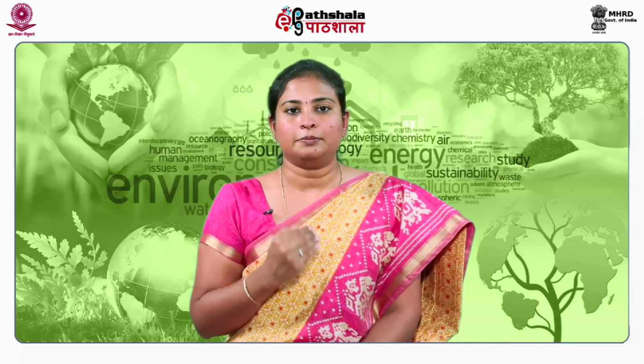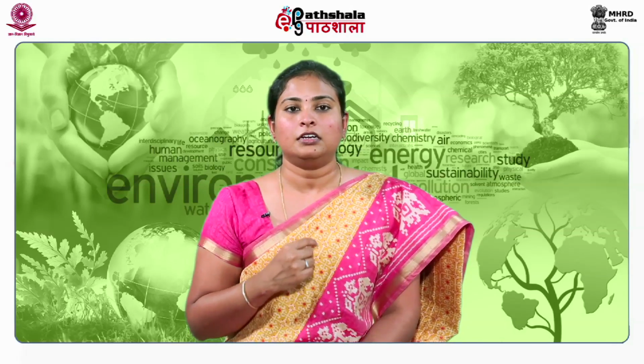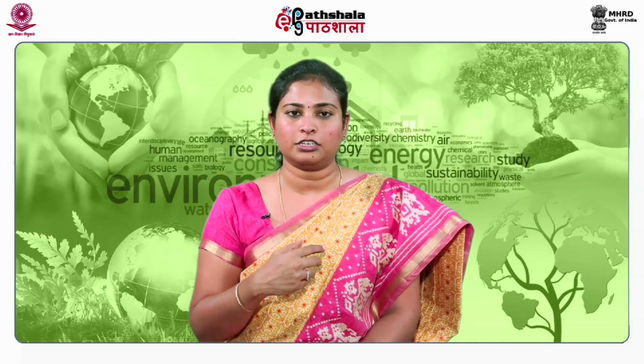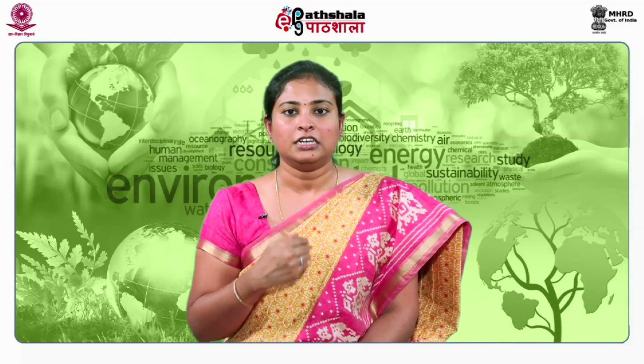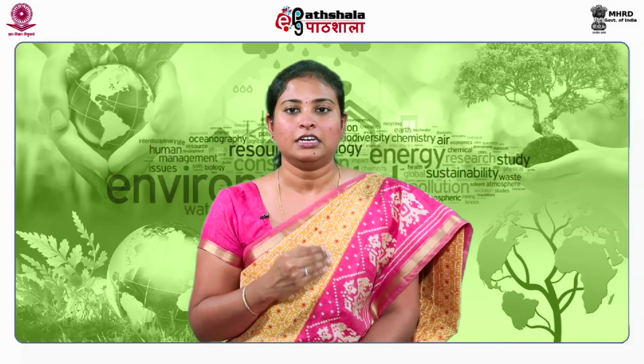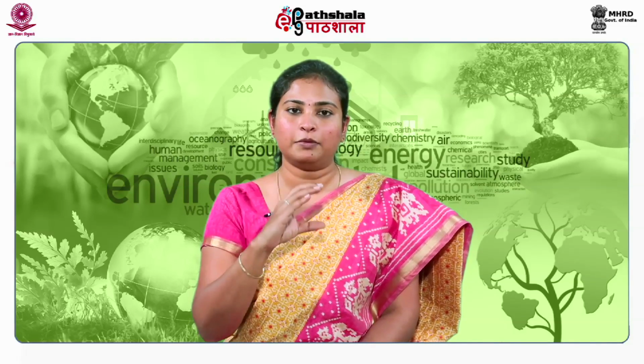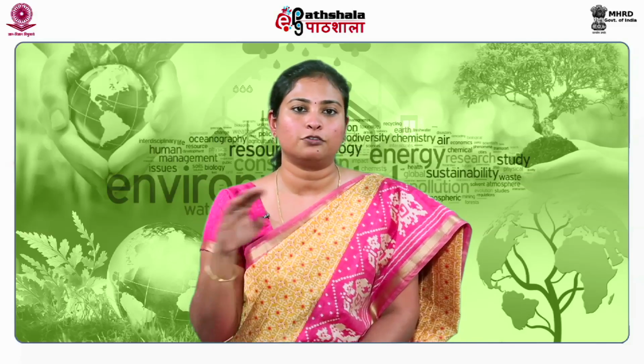Now, the next component is the daily and final cover at the top of the landfill. The cover protects against the entry of water into the waste during precipitation. The cover layer is composed of synthetic and natural materials. For daily cover, about 150 mm of soil is placed on each layer of waste.